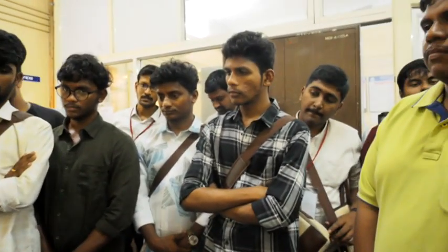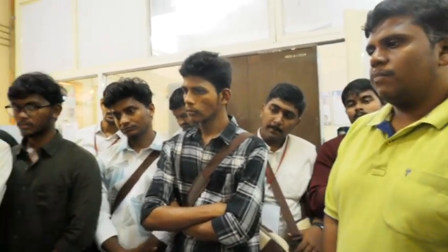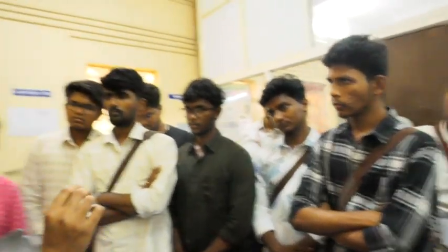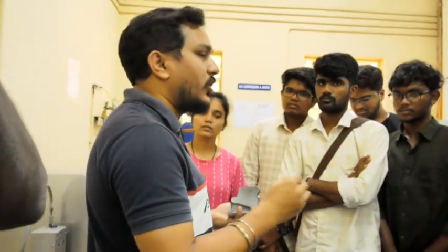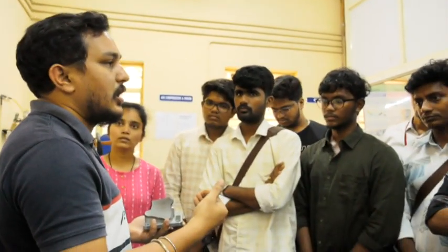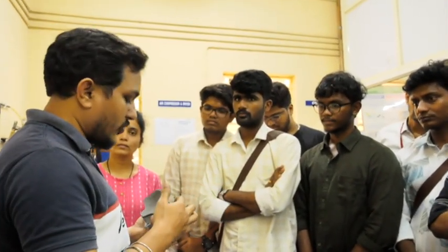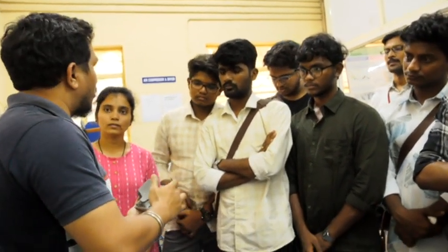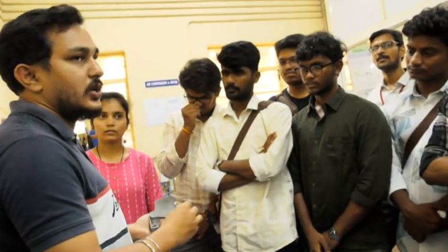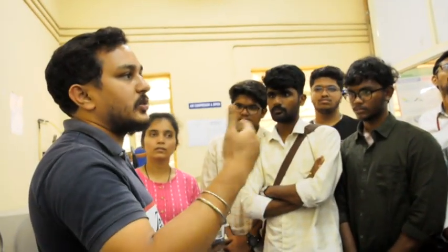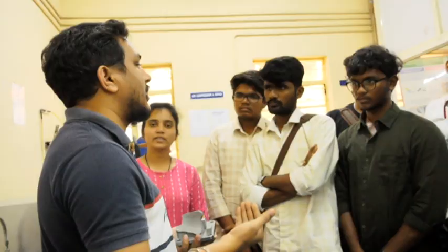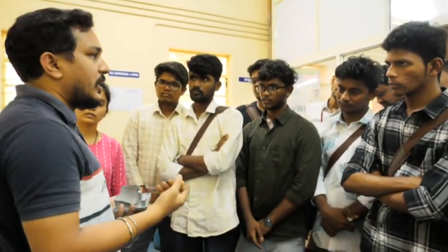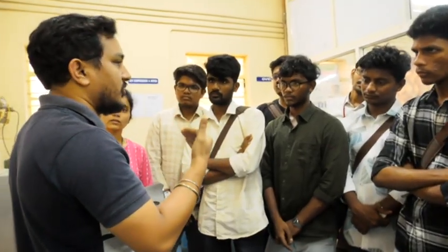Then for normal solid samples in LPBF, mostly near net shape components will be obtained. But we still need a smoother surface. Here you can see some roughness; if you touch it, you can get to know there is some higher surface roughness. In that case, there are some post-processing techniques, like shot peening or sandblasting and those things. That will help you reduce the surface roughness.